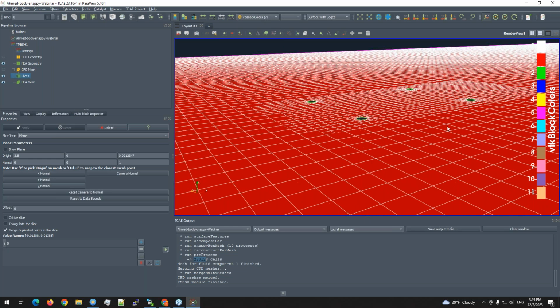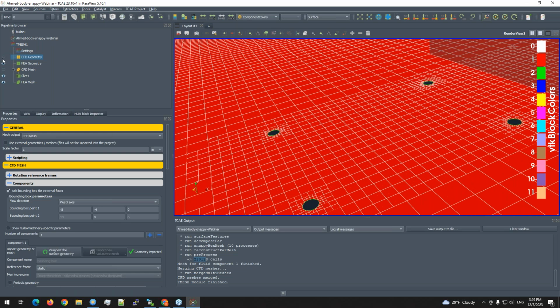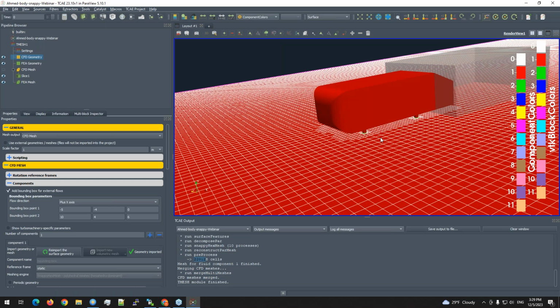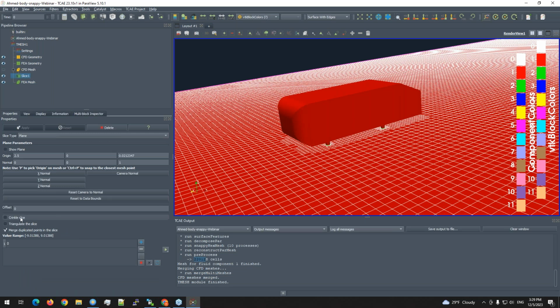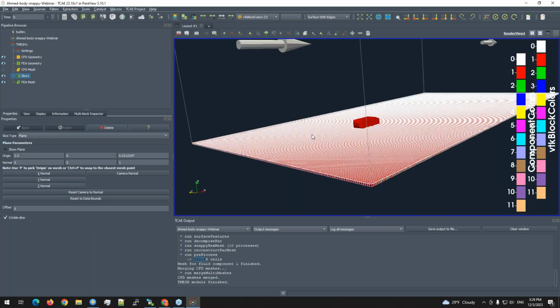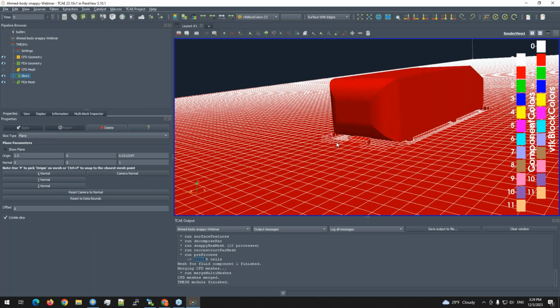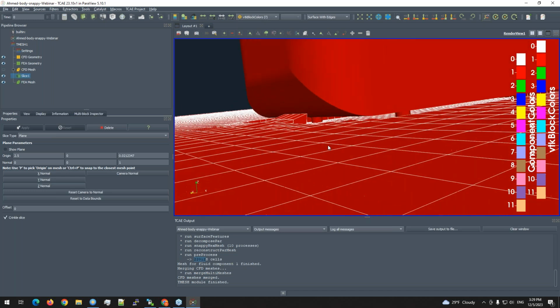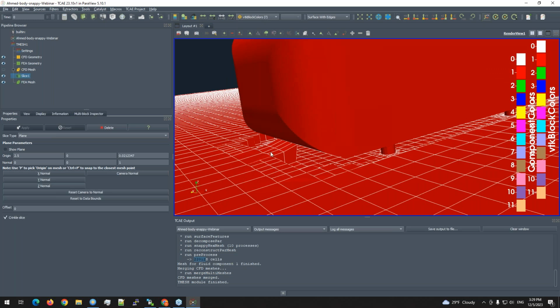Thanks. Yeah, and what I would like to check, for example, is also if the stands are meshed properly, so we can see that we have nice meshing around the stands. And as Lubos mentioned, we can also enable this crinkle slice, which really visualizes the full shape of the cells which are intersected by our slice. As you can see, all the cells which are intersected by the slice are shown as 3D cells. So this is basically the real shape of the generated cells.